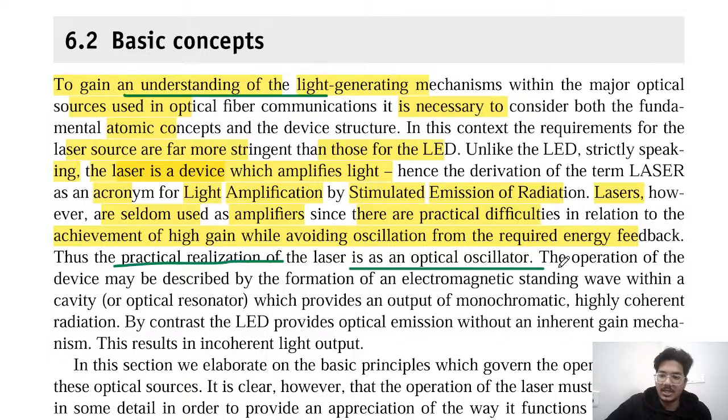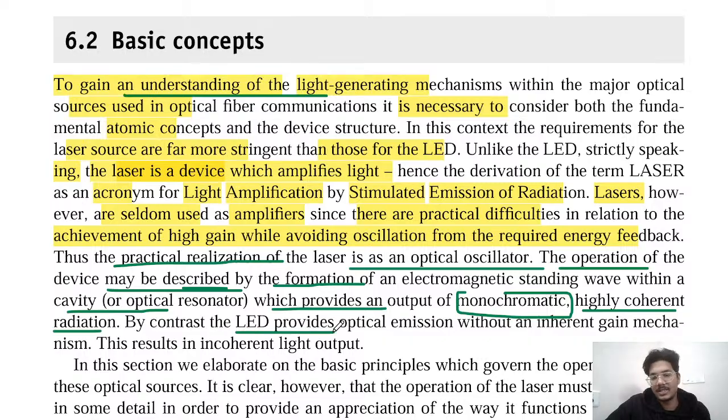The operation of the device may be described by the formation of an electromagnetic standing wave within the cavity, which provides the output of monochromatic, highly coherent radiation. By contrast, the LED provides optical emission without an inherent gain mechanism. This results in incoherent light output.